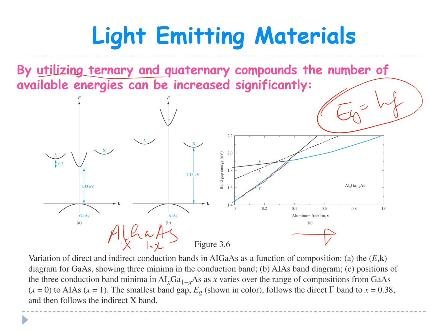Up to here the band gap is direct. Within this region you can have your band gap varying from something like 1.4 to around 1.8 electron volts, so that's a very large variation. Depending on the composition of your aluminum, you can tune the color that is emitted by your PN junction. So these are all important things to remember when you think of light emitting diodes.